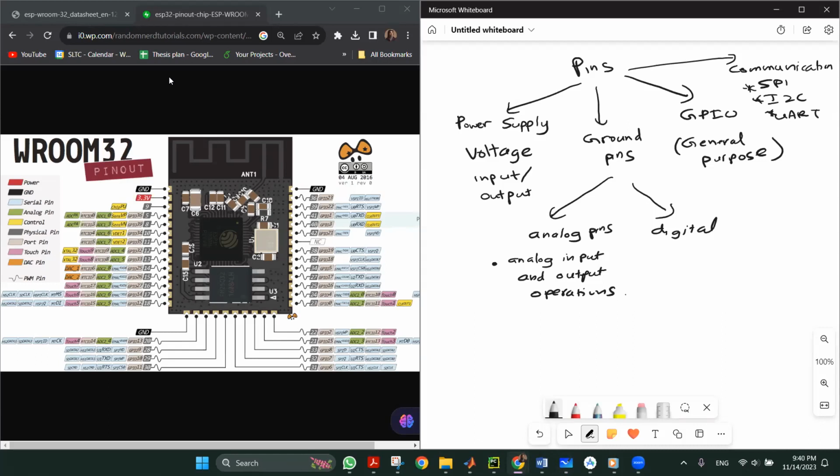So we have to know some specific details regarding the pin configuration of the ESP32. Once you refer to the data sheet and the other resources available regarding the pin configuration, we will be able to see exactly what the pins are and what pins are for what. According to the data sheet, there are 18 analog to digital converters, ADCs. These are able to convert the analog signal that we input to the microcontroller to a digital signal. So there are 18 pins of that.